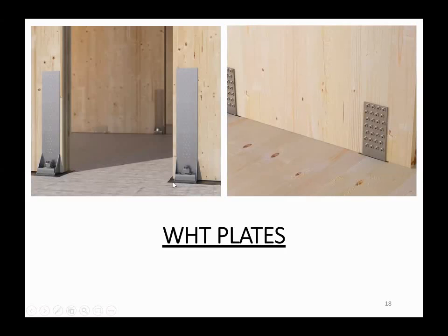Here you can see in the detailing, they've installed a waterproofing membrane underneath the CLT panel, and that's to stop any capillary action, or moisture from the concrete, entering the bottom of the timber. Once again, this connection is nailed. It's got a hold down washer and a bolt into the concrete. This one has been slotted through the CLT floor to the panel underneath. This is held in position with a panhead screw.